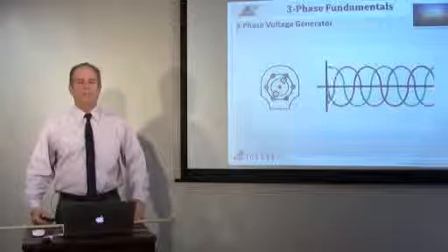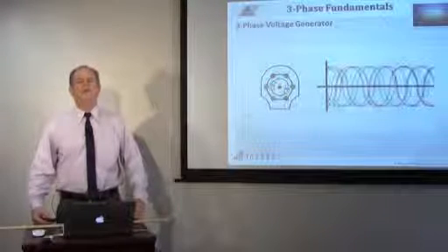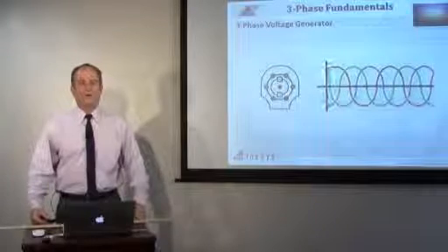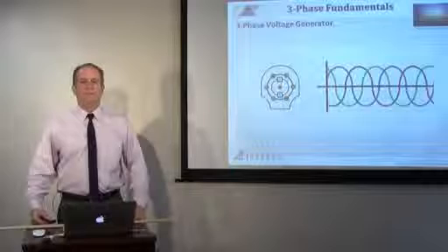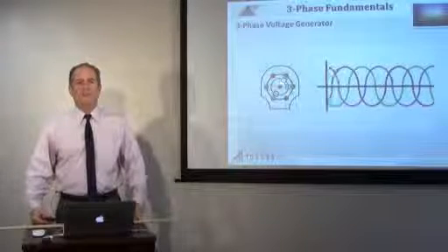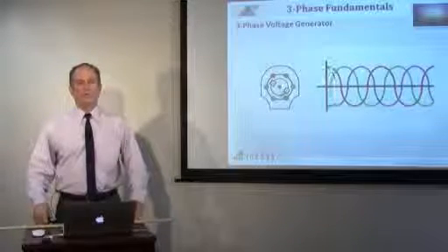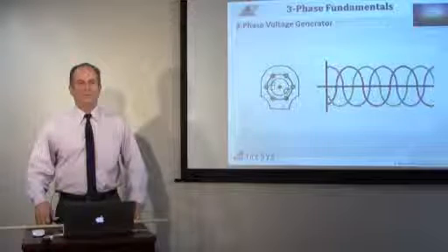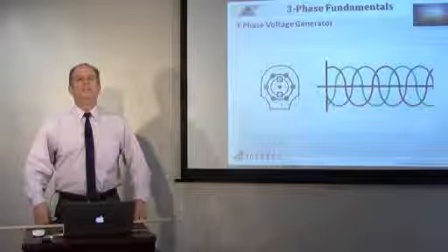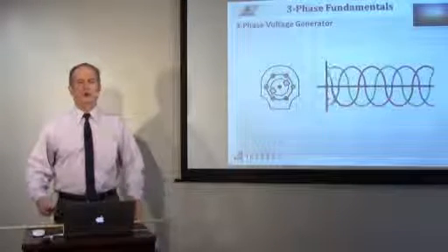And that's one thing about a three-phase power system, is that these generators are producing power and we are consuming power in real time. We're not storing any three-phase. We're not saving it up for later. We're just operating it as we generate, as we load it up. So our generation is really adjusted by how much load we have. As people are turning on and off light switches, the generator is ramping up or ramping down in the system. So it's all real time.